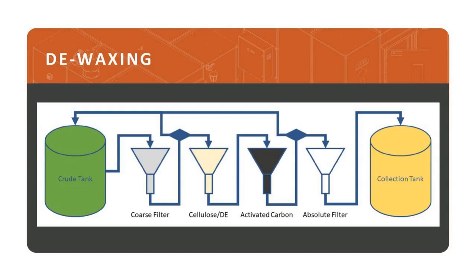Typically, this vessel will be jacketed into a chiller. The entire apparatus actually might be a walk-in freezer, for example. But the idea is to get that vessel down to those sub-zero temperatures. So again, ideally as close as possible to negative 80. Celsius, I should say. It's a little bit harder to achieve for dewaxing. Obviously, it's hard to kind of put the entire unit in a sub-zero freezer. But if you're getting below negative 20 degrees Celsius, you're going to see some good results from your dewaxing.